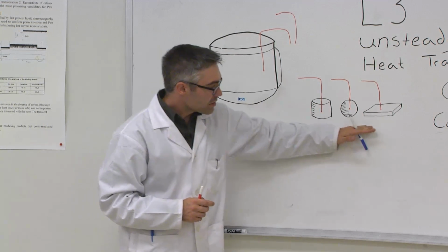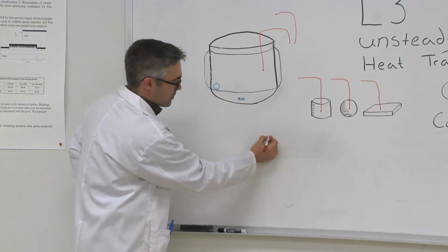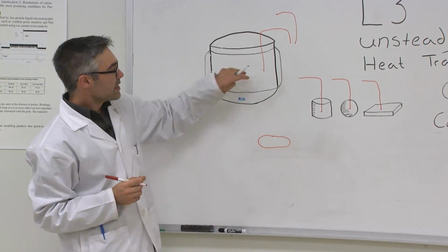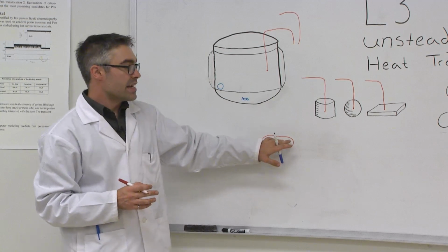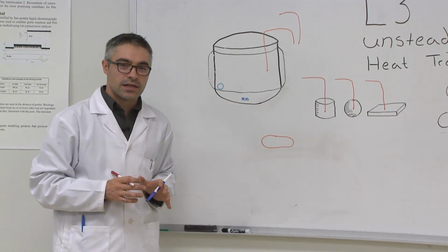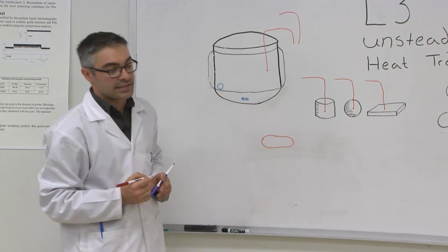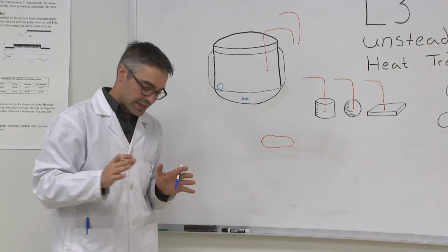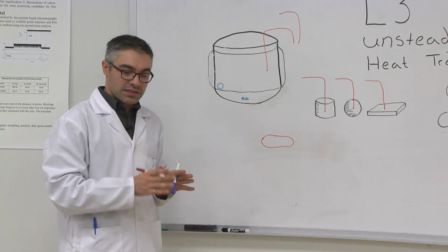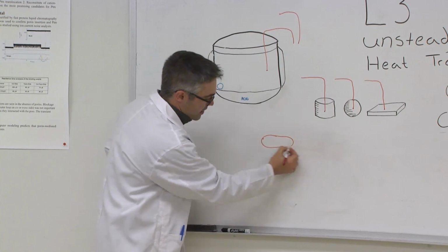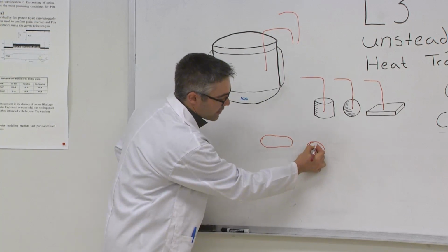Often, shapes aren't ideal. For the second part of this laboratory, we're going to be immersing a potato, an irregularly shaped potato, into our water bath, and we'll be observing the temperature gradients within the potato and comparing to our idealized shape factors. The way that you're going to do this is the flesh of a potato, the starch, will begin to gelatinize at a very specific temperature, and you can watch this gradient pass through the potato as time goes on. At certain time increments, we'll be slicing the potato open and observing the starch gradient as it moves to the center of the potato.